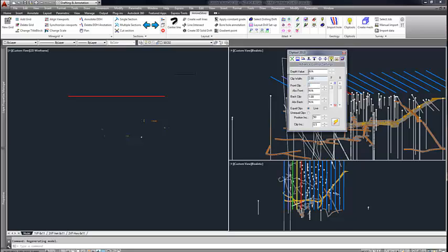If I want to have 1 meter or 1 unit, I click on that, and you'll see the bottom changes at the same time as the top because I'm set to equal clips. Equal clips mean that the front and the back stay exactly the same distance apart from the center point. So my center point is this line, and I'm now half a meter in back of it and half a meter in front of it. You can see just a little piece of my drift showing through. The reason why it shows as a dashed line is because I'm just seeing a little piece of it. It doesn't actually close it. This is a clip, a quick clip. I'm not physically cutting the sections.